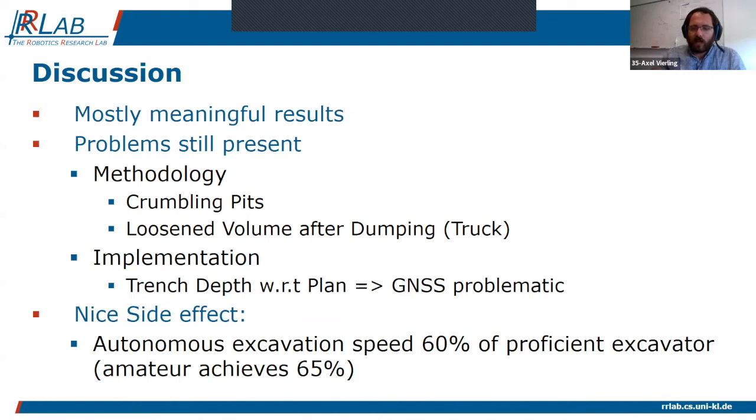We tried to solve this by not taking only the grid cells of the exact target pit, but also the neighboring grid cells. This improved things, but this is still, let's say, a weaker point of this methodology. Also, of course, we only consider the loosened volume in the bucket, but not, for example, when loading into a truck, where the soil becomes even more loose.